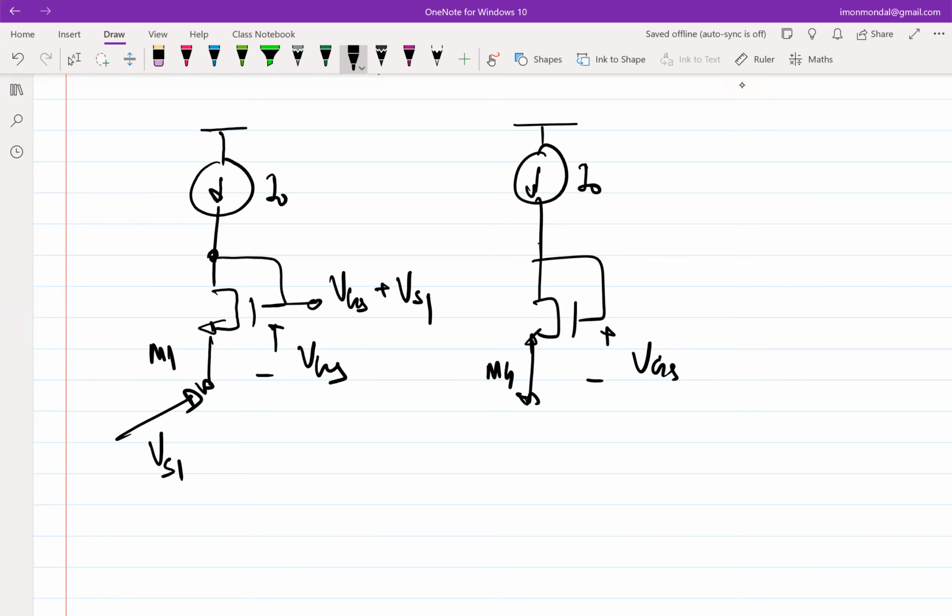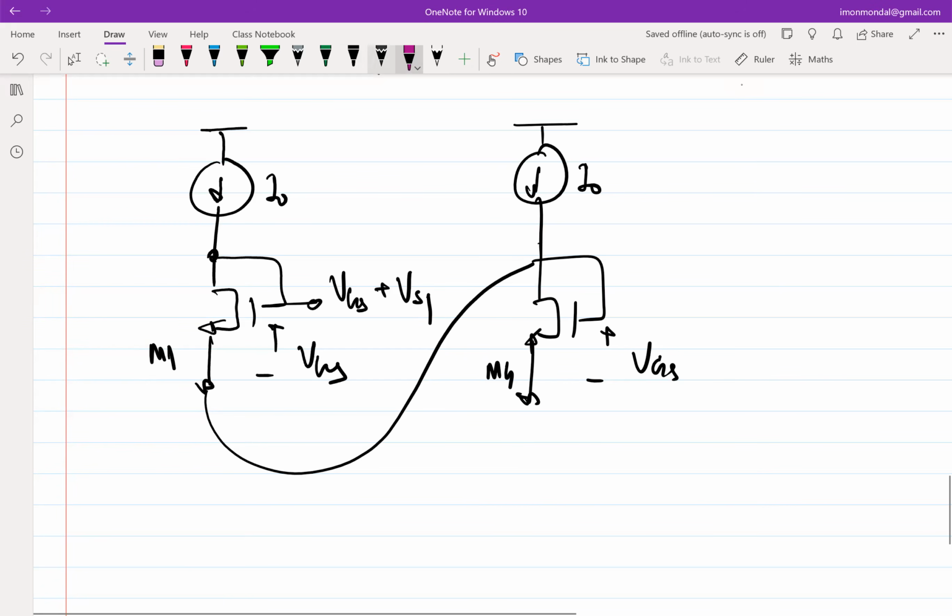VS1 to the drain. Right. So essentially, what we are looking for is another... So if we connect this to here, right? If we connect this to here, this is not the solution I'm looking for, simply because you are seeing a current division here also, right? At this node between the I0 on the right branch, because now the transistor M4 is trying to get 2 I0 current.